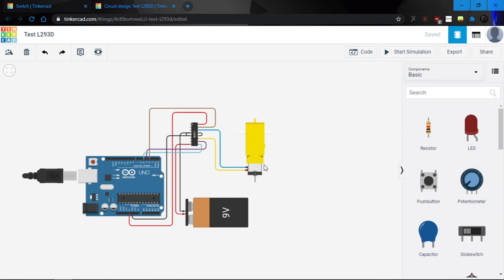And the second issue is, if you use a lot of motors and share the power source with the Arduino, it will be hard for the Arduino to work, and sometimes it will force the Arduino to restart the board. So if you're doing any wireless project like Bluetooth or PS2 or any other wireless, it will be disconnected and then reconnected, and this will be a problem for you.